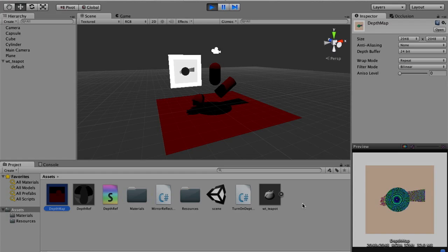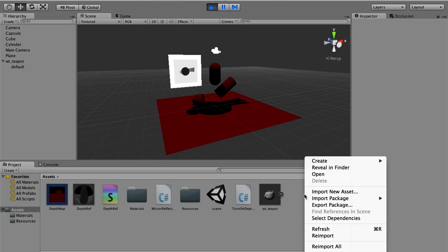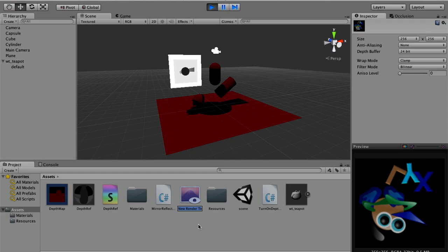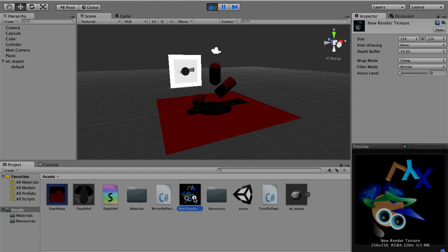So to create these render to textures, it's quite straightforward. You just, within your asset view, go create, and you will see render texture. I'll just create one. I won't use it for the rest of this, but you will need to do this for every light in your scene in order to create textures for the shadow mapping. So all the lights, sun and two spotlights in your scene, will require you to create multiple render textures, because, as per the theory, each depth map represents the view of the scene from the light's point of view. All right, I'll delete that because I don't like leaving things untidy.